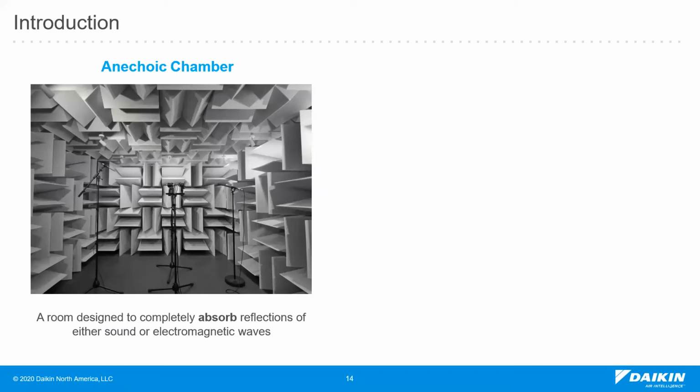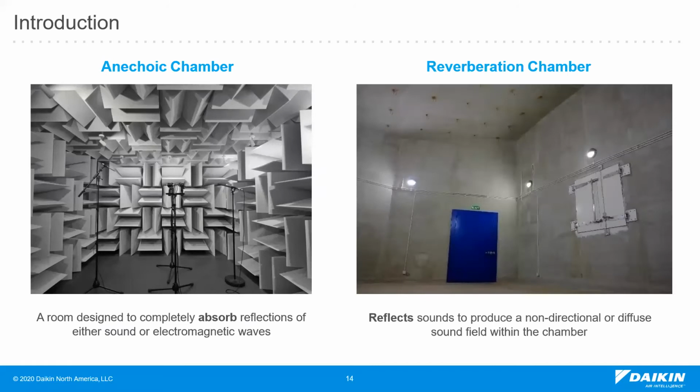AHRI 260 sound power data is available for ducted units, and this data is obtained by testing in a different environment. This is called the reverberation chamber. The reverberation chamber testing environment will reflect sound. It diffuses the sound field within the chamber, as opposed to the anechoic chamber, which absorbs reflections of sound.